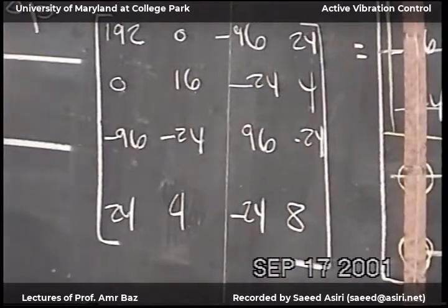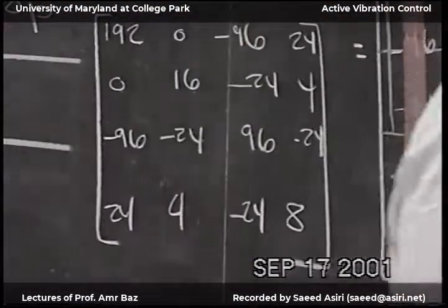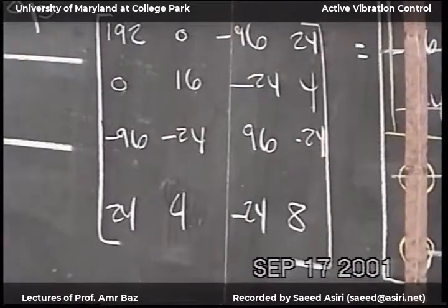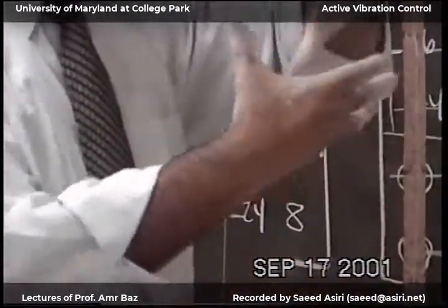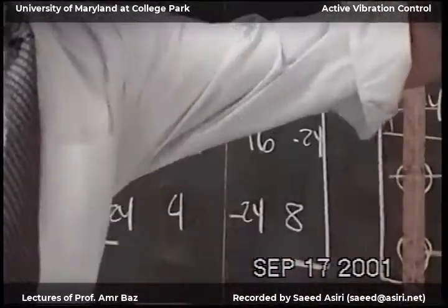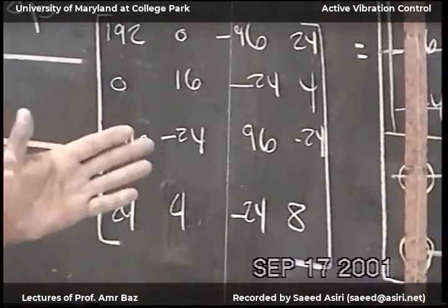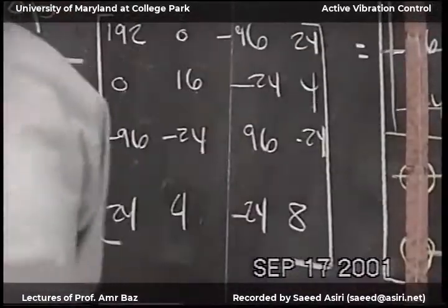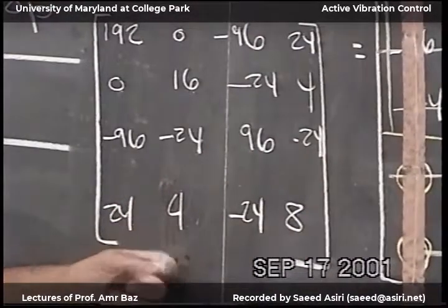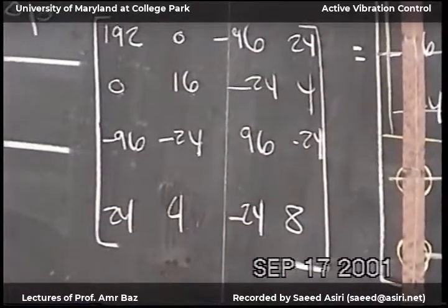So now, from the individual element, I assemble the overall matrix, impose the boundary condition, eliminate the columns corresponding to 0 degrees of freedom, and also the rows. Then the reduced matrix is like this. Okay?